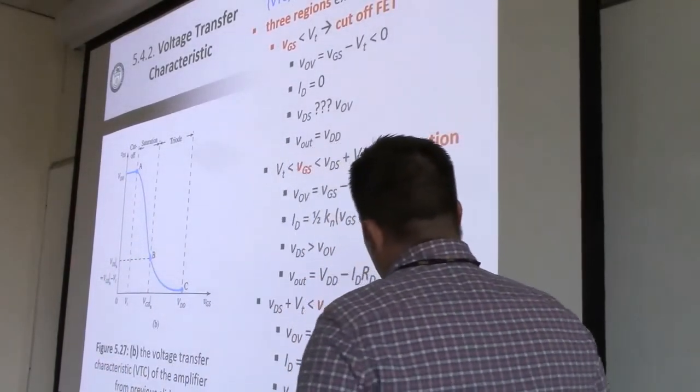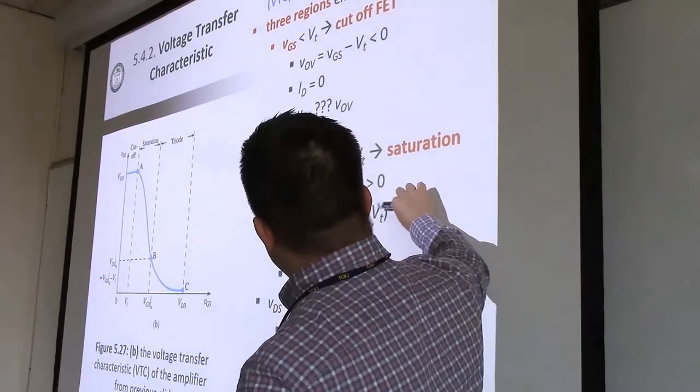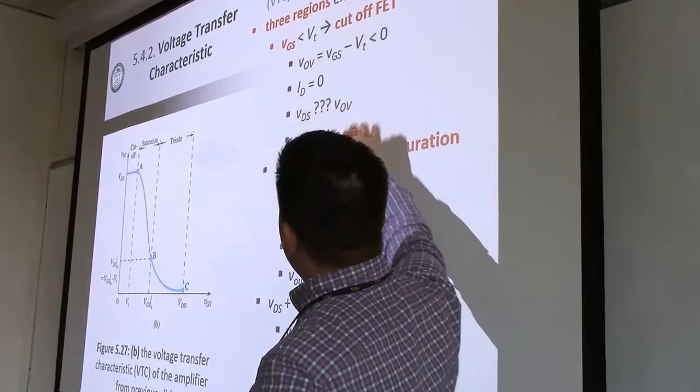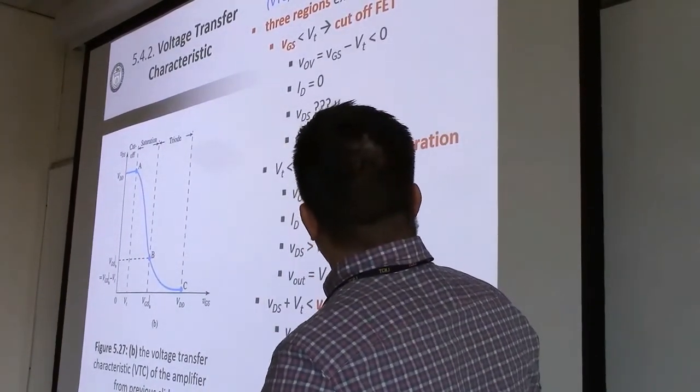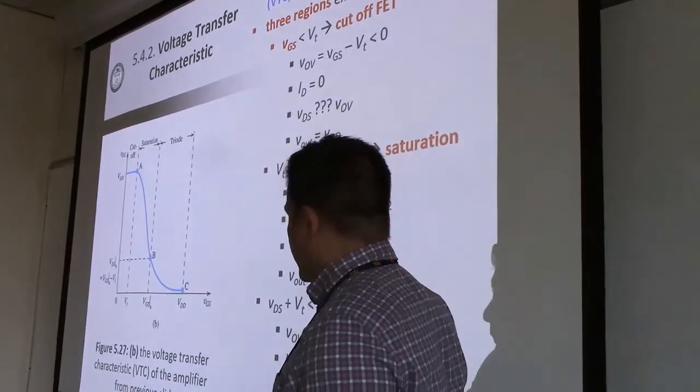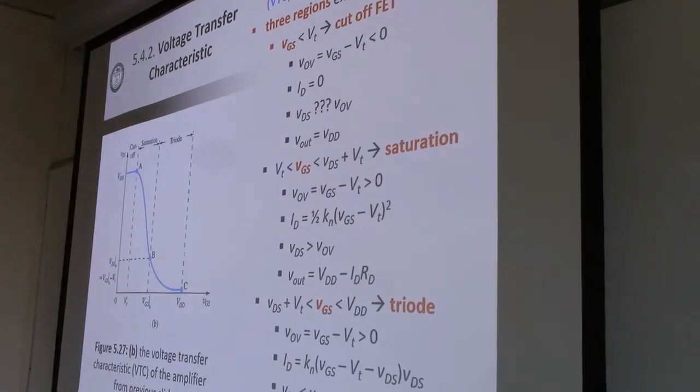Okay. This equation here is the ID-VI relationship for triode region. This is the VI relationship for saturation region. And in the cutoff, ID is equal to 0. And then this is always the same. Overdrive voltage is VGS minus VT. Okay? So not really any new material in those bullets, but when we do these amplifier-based problems, sometimes it helps to have everything in one spot.